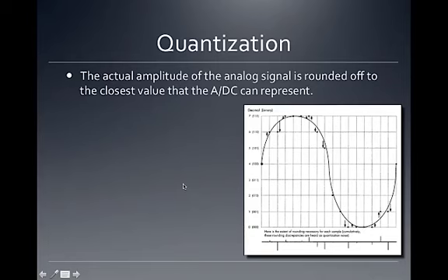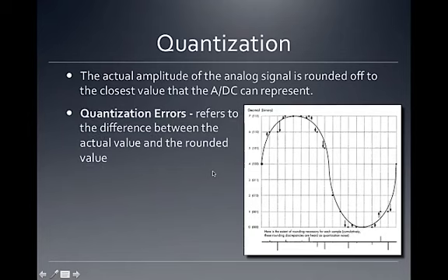So this graph is representing this concept called quantization errors, where if we don't have enough bits, so let's say in this example we have a 3-bit word. I mean, that's really weird. We never really record anything at 3 bits. Probably the lowest you've ever heard of is recording something at 8-bit. But 3-bit gives you a good representation where we have an analog sine wave, one cycle that's trying to be sampled, and you see there the dots is wherever all the samples are being taken.